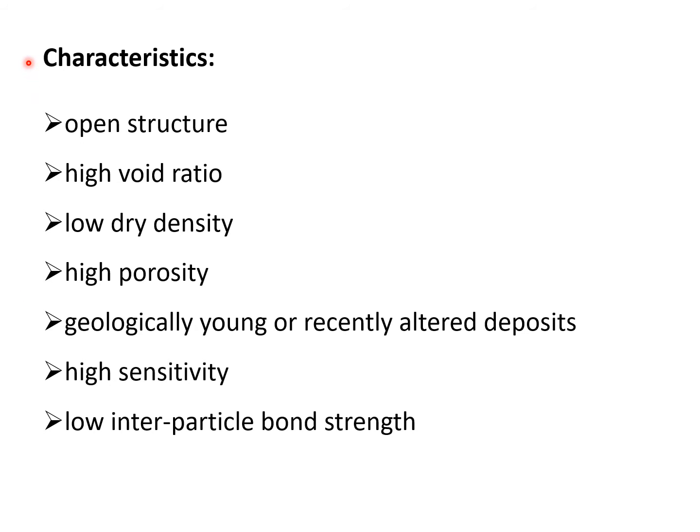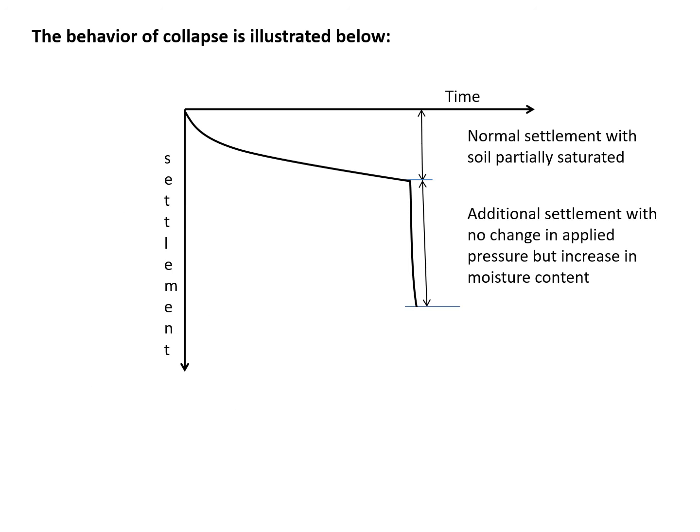Characteristics of such soils: open structure, high void ratio, low dry density, high porosity, geologically young or recent altered deposits, high sensitivity, low interparticle bond strength. The behavior of collapse is illustrated below.